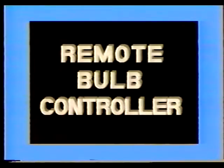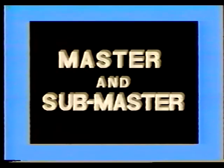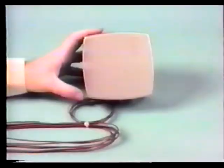Prior to the advent of the transmitter and receiver controller systems, remote bulb controllers, often referred to as master and submaster devices, were utilized. These controls had limitations as to where they could be located. The mounting location could be no further from the sensed medium they were controlling than the length of the capillary tube attached to the temperature sensing bulb or the pressure capsule in the case of pressure sensing.